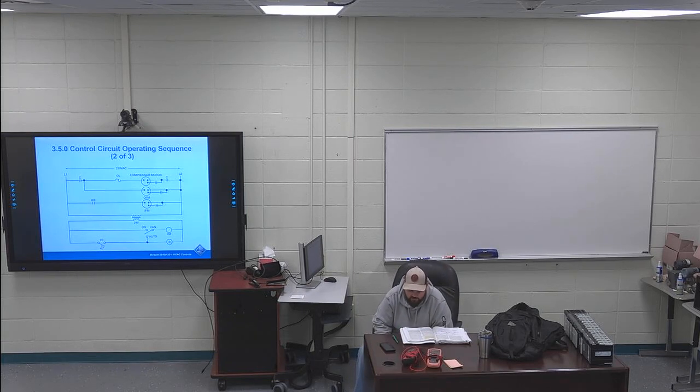No matter how complex the control circuit appears to be, you will find the basic control arrangement shown in figure 36 or something very much like it at the heart of the circuit. Everything else will be special features to improve equipment safety or operating efficiency. This is illustrated in figure 37. This diagram is for a combined cooling and gas heating unit. The circuit looks different and there are several more components. However, if you trace the cooling control function, you will see that it is essentially the same as that previously shown. The differences are that the heating controls have been added near the bottom of the diagram, along with the heating cooling thermostat. Key in on this sentence.